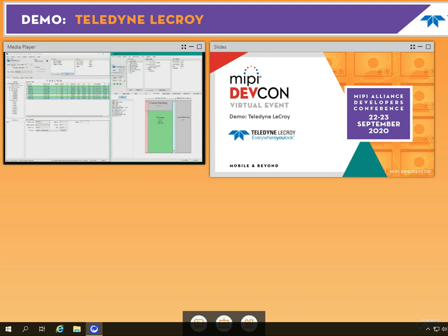The Video Analysis tab reads the event file and gives a summary analysis of all the frames. It shows how the frame looks relative to transmission. The user can confirm line starts, frame blanking, frame starts and ends, line ends, and line blanking. The Envision X84 will distinguish line blanking done with low power states or with blanking packets. The analysis also shows the frame rate, the resolution, the average amount of time spent in blanking periods, as well as payload size and errors.